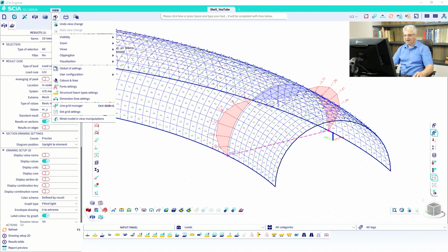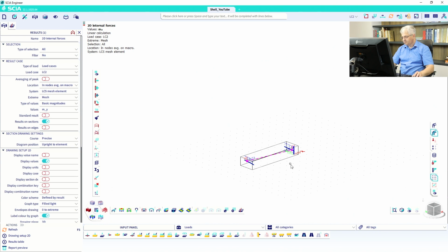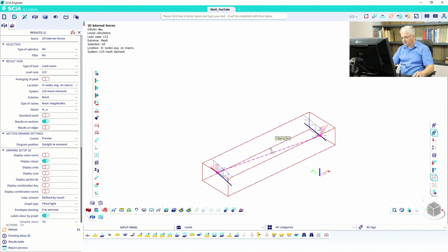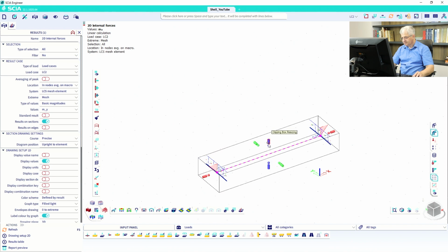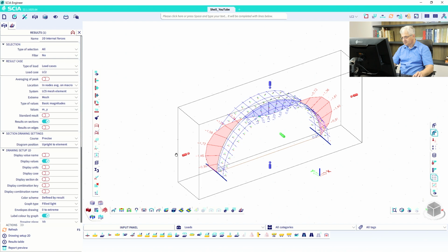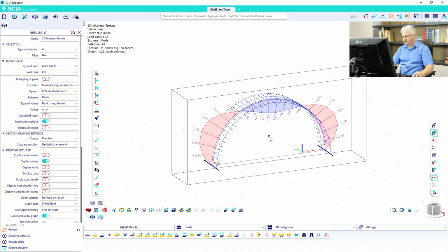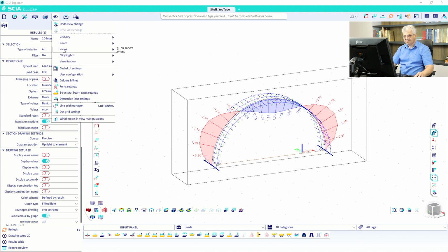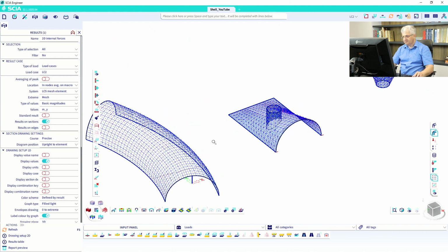If you want, you can combine all these 3D results evaluations with clipping box around selected entity. This is my only my section, and I can select it. I can rotate it a little bit, so better, make it higher and wider, so I see one section of my tunnel tube. So, and then you get your results. Okay, deactivate it. We are in the finish. Control Q to see everything.